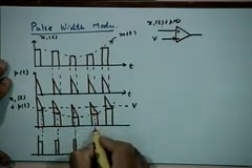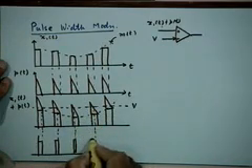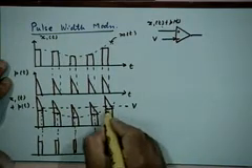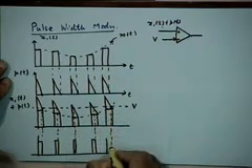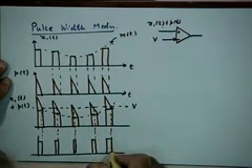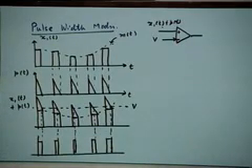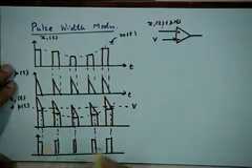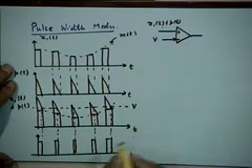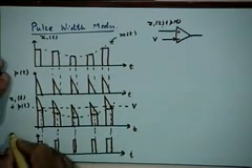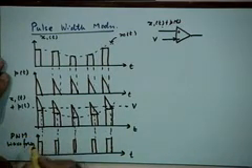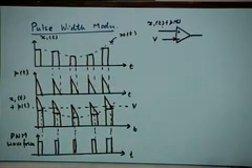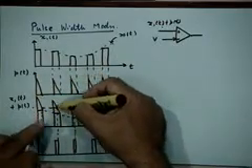As you can see, the width of the pulse that you will generate will be proportional to the amplitude of the pulse on which the triangular pulse is riding, and that's precisely what you want, right? So this becomes your PWM waveform. Are you with me? In fact, it is obvious because of the fact that this is a triangular pulse.